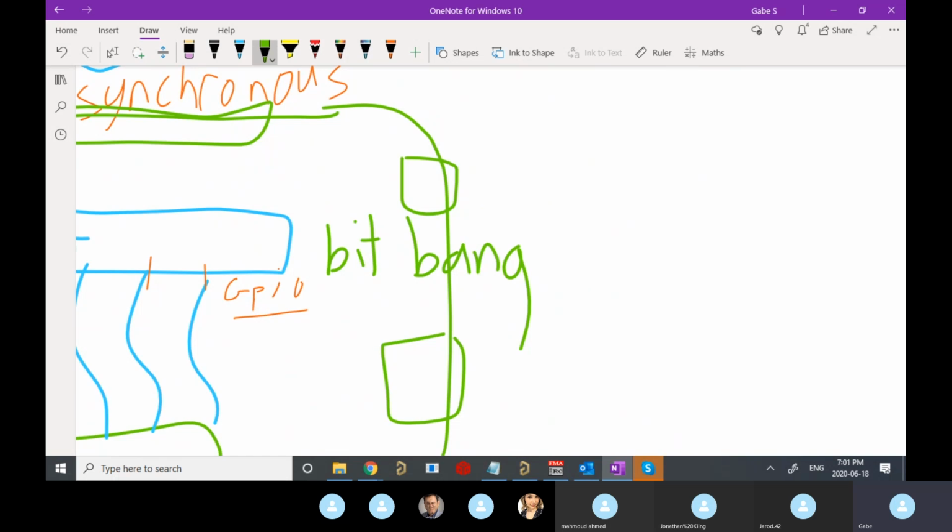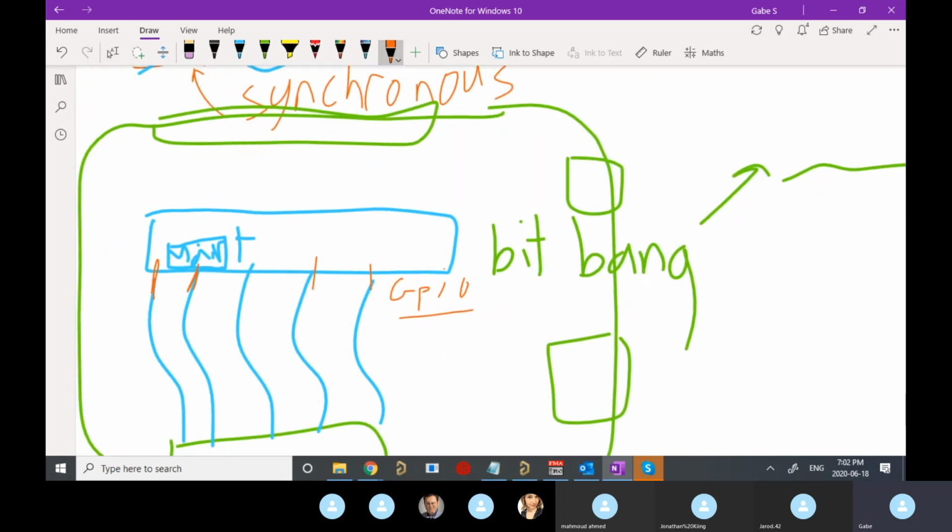It's not going to be as fundamentally fast because that hardware isn't in place to do exactly those transmissions. And you're going to have to write a lot more code to actually write that protocol yourself. So usually with that hardware block in place, you're going to get a driver function for that. And basically all you would have to do as the user is say UART send in your function, and then my data, right? And then you can call it a day. You'll have to initialize it and do a few other things, but that's essentially the gist of it.